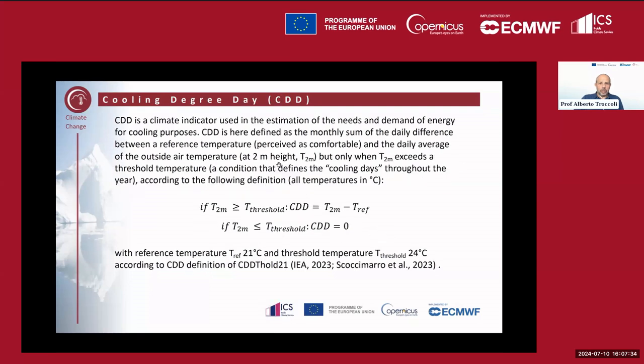And cooling degree days is a kind of mirror image of heating degree days, and is here defined as the monthly sum of the daily difference between a reference temperature and the daily average of the outside temperature. So very similar to the heating degree days, but here it is when the temperature exceeds a threshold temperature, a condition that defines the cooling days throughout the year.